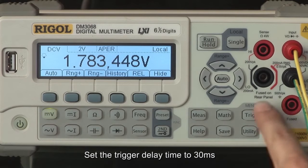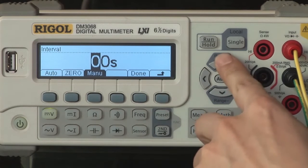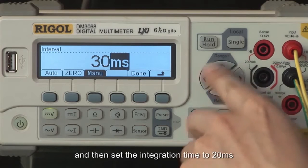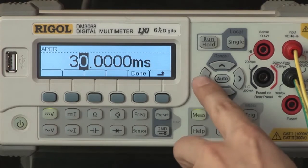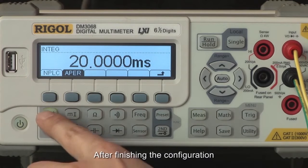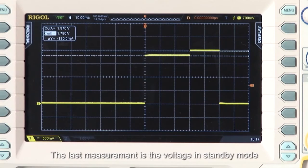Let's set the trigger delay time to 30 milliseconds. And then set the integration time to 20 milliseconds. After finishing the configuration, you can see that the multimeter displays the transmit signal. The last measurement is the voltage in standby mode.